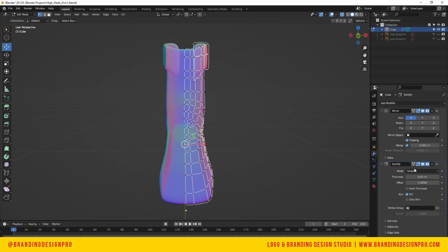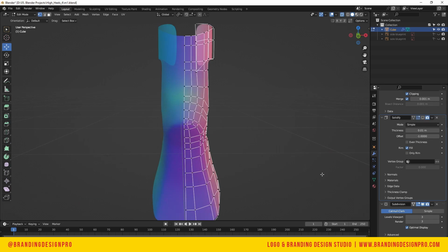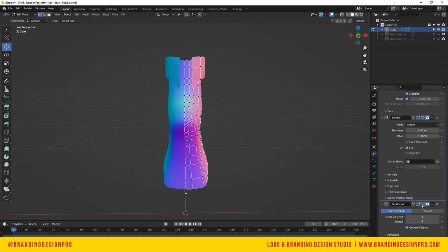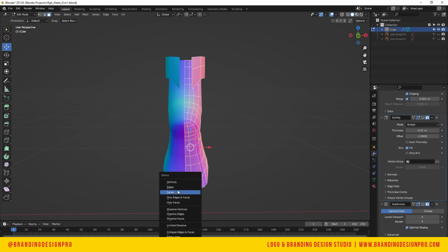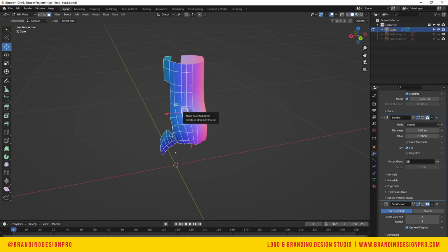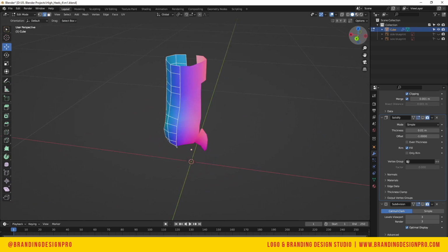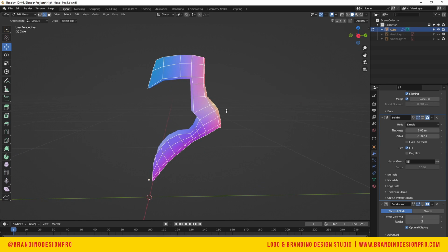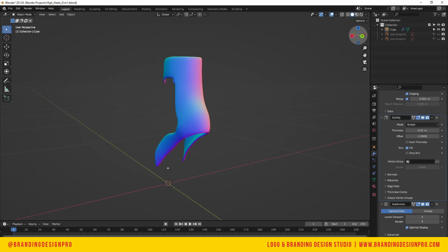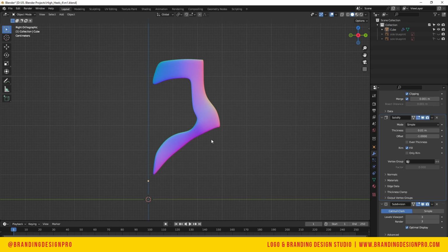And then we're going to then go to the front mode. In the subdivision surface, we're gonna turn off the display view and then go ahead and select the faces of the bottom and X delete. Then we're going to select a couple of the edges and dissolve 2 of the edges in the back to make our geometry a bit more smooth. There'll be less bumps or no bumps at all towards the back. Let's see, and tab out.